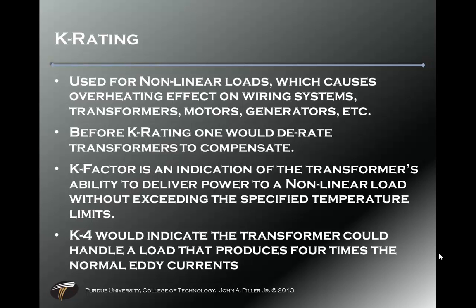So basically, I'm going to use some numbers here, but let's say your load needs a 100 kVA transformer. We're just going to put on a 150 kVA transformer so you can handle that extra ampacity that your nonlinear loads would do. K-factor is an indication of the transformer's ability to deliver power to nonlinear loads without exceeding the specified temperature limits. A K4 would indicate that the transformer could handle a load that produces 4 times the normal eddy currents. We're going to talk about what eddy currents are.